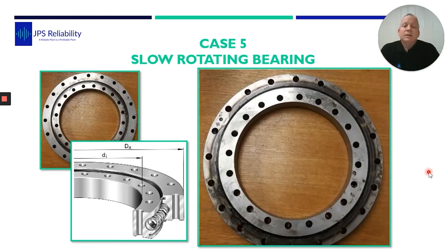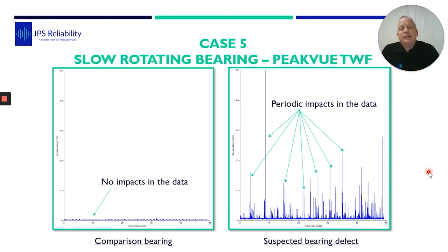There were lots of doubting Thomases on whether we can actually pick up a defect with vibration analysis because it's going so slow. But the high frequency where we're sampling, you're getting into the ultrasonic range anyway, getting up that high. This was our first data. So we chose PeakVue and we were using the time waveform, and we were sampling them really high.